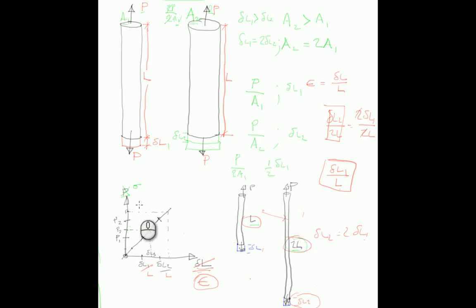So that is why we use these variables, or these quantities, these characteristics of the sample, stress and strain, instead of what we originally looked at, which seemed an intuitive way of looking at it, the force that we applied compared to the change in length. And the reason we've done that is so that we can look at a value which allows us to compare all samples regardless of their original length and regardless of their original cross-sectional area. Okay.